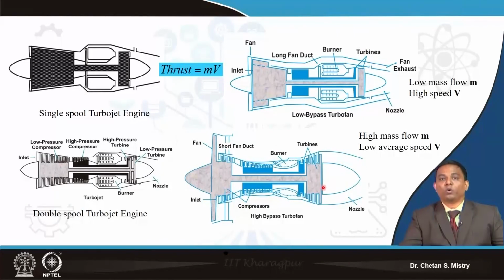Now here also, as we discussed, our major concern for aero application, say for commercial airlines, is fuel economy, and we can increase our fuel efficiency by increasing turbine entry temperature, but we have a constraint with heat transfer. So in order to address this, we have this big size fan that gives the bypass air which can cool this particular region, and that gives an additional benefit.